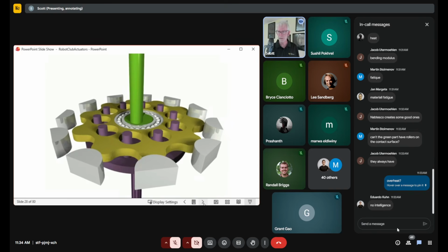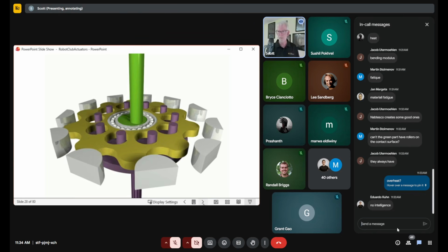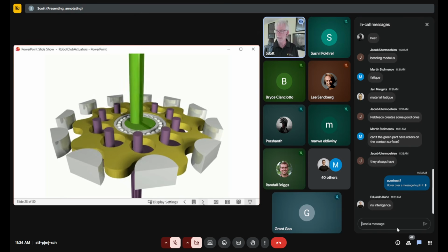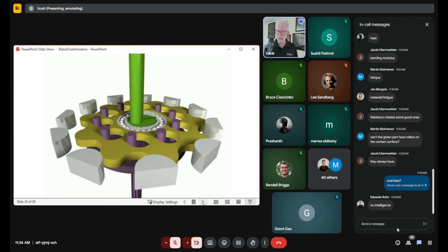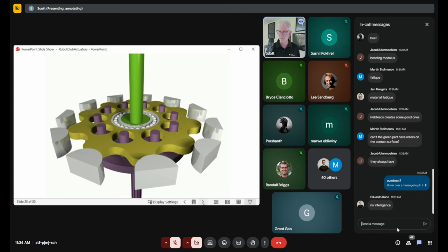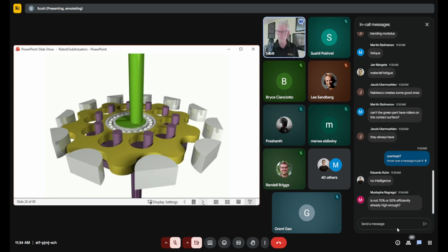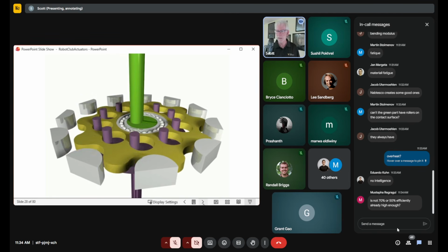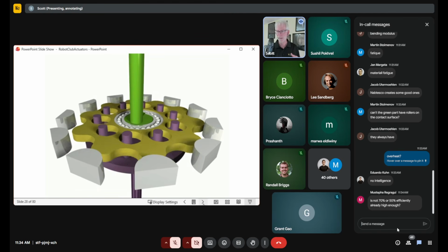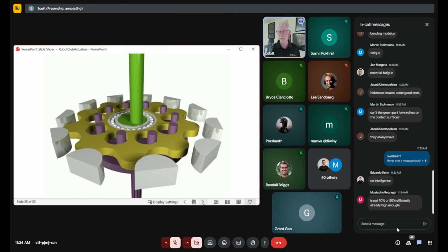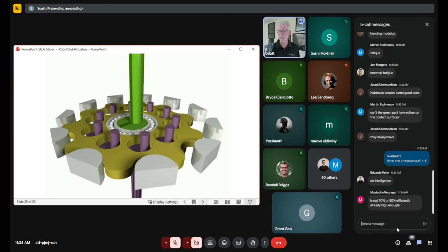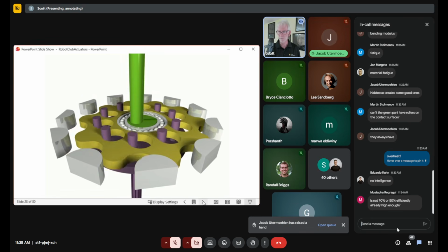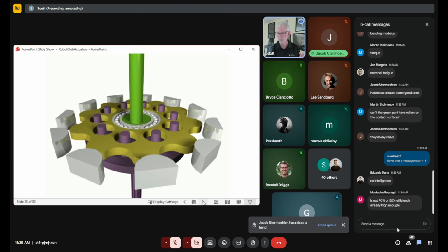So, for instance, a cycloidal, which is again a very bizarre mechanism, is starting to be popular because it has efficiency in the high 90%s. And in theory, it looks like it might be pretty easy to make, because for the precision you need for gears and stuff like that, you need grinding machines, and in theory the tech should be a lot easier. But that yellow thing that you see in the middle there, you've got to get the shape of that thing right and manufacture it right. So it turns out it's much harder to make these cycloidals. But if you can, they have zero backlash. They don't produce as much heat because they're very, very efficient. They have almost the same space efficiency.